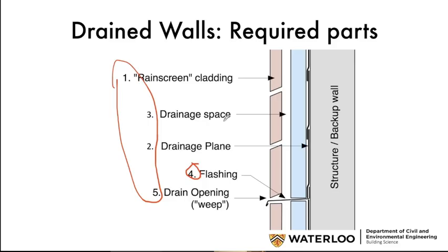Anyway, so leaky cladding, drainage plane or water resistant barrier, or sheathing membrane. All 3 terms are building paper. All these things are used. There needs to be a gap to allow water to flow, and you need flashings and a weep hole. And as Marley was asking,